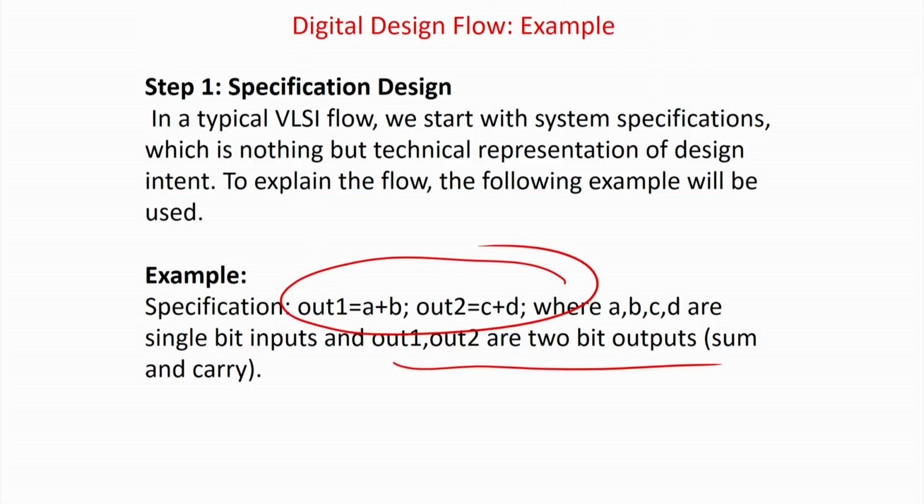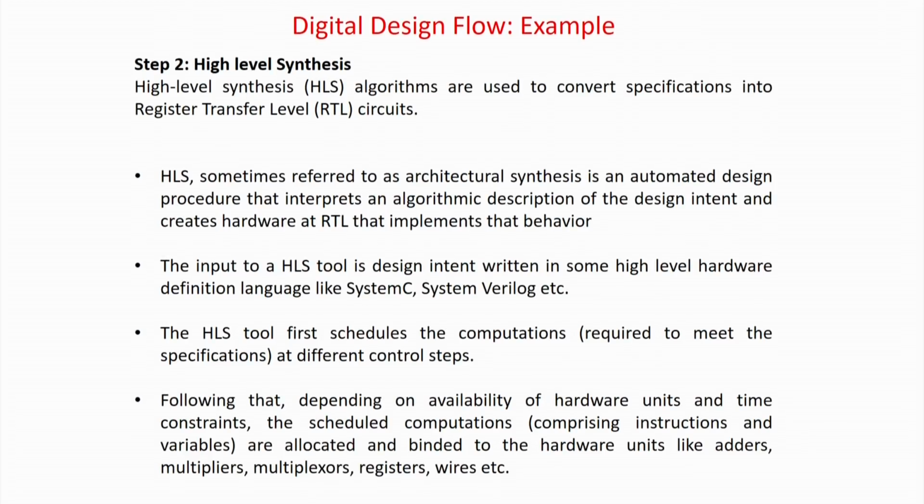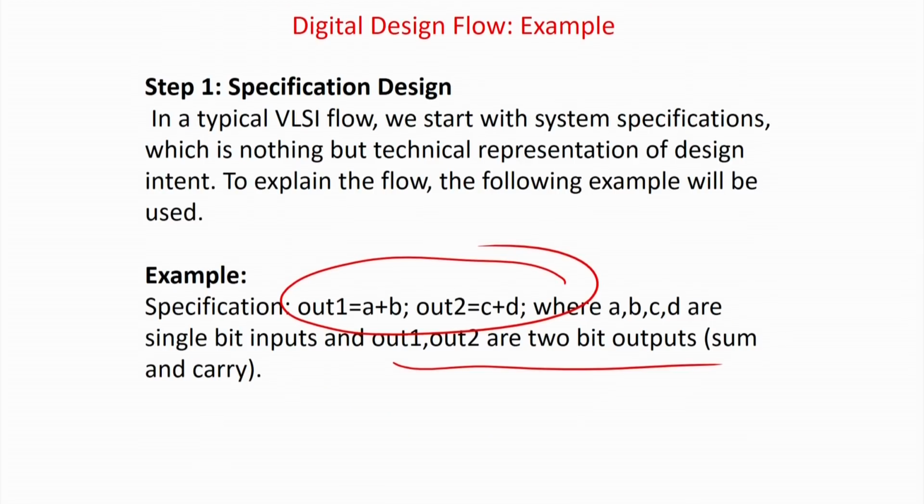But if it is more complicated, then you have to think. For a processor, you can understand that there will be a full manual or a book where these specifications are written. Then you have to think where to put adders, what multipliers you will require, what the broad circuit diagram will be, etc. But in this case it is a very simple specification, so you can just think an adder is required. Maybe you can also say a simple half adder will do, because there is no carry business here. From the specification and block level diagrams, maybe I can just think that you will require a block with A, B, and there will be some sum out and carry. I do not require anything else. The same block level diagram you can think from your mind.